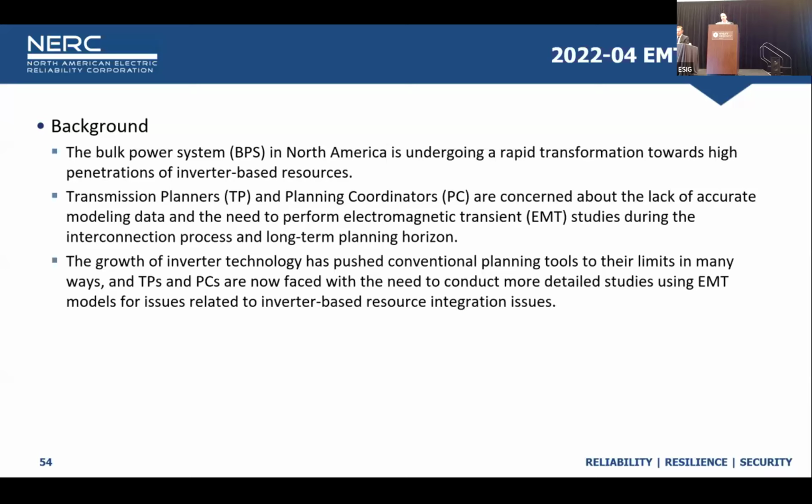Now, the growth of the inverter technology has pushed conventional planning tools to their limits in many ways. And on a side tangent, coming from the HVDC industry, the original IBR, this has always been the case for us. So this is not something new that we're introducing. But now the TPs and PCs are being faced with the need to conduct much more detailed studies using EMT models for the issues related to this resource integration.